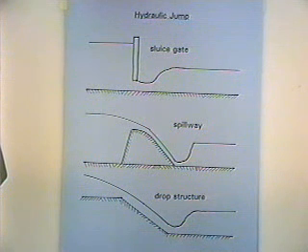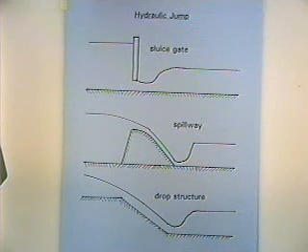There's a tremendous amount of turbulence in a hydraulic jump, and the turbulence dissipates the energy. And so in many cases that gets us into trouble because it causes erosion of natural stream banks. In many cases we use it to our advantage to dissipate energy on purpose in an engineered type of an energy dissipator.